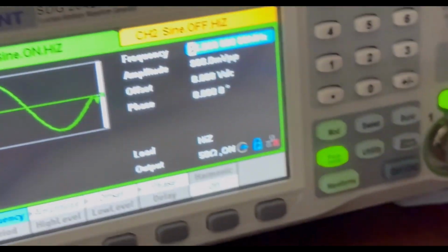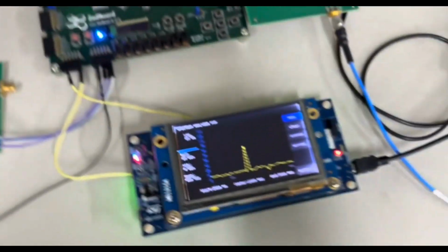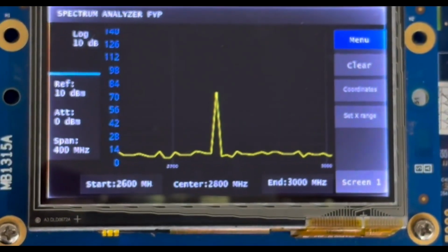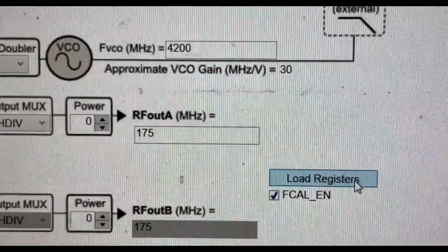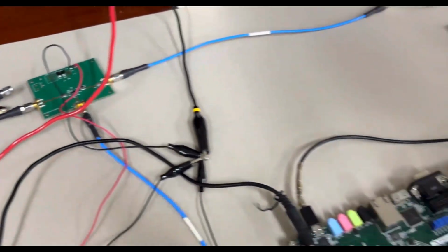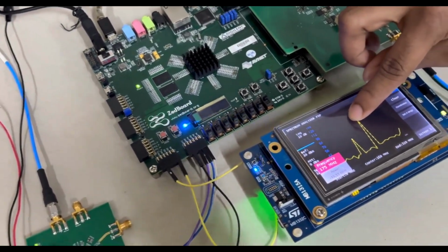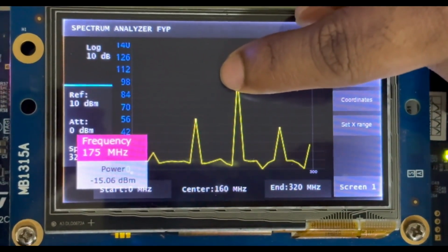We have successfully built a modular scalable spectrum analyzer that delivers accurate results at a lower price point. The minimum resolution bandwidth is 5 MHz and can be extended to 1 MHz with the same hardware setup, as the limitation here lies in the filter bandwidth and the display rendering capabilities. The sweeping time is around 180 milliseconds for 300 points, and the maximum RF signal power it can handle is 10 dBm. Due to losses in the standalone PCB connectors, wires, and the use of non-low-loss PCB materials, the minimum detectable power is negative 30 dBm. However, with an upgrade, we can detect much lower signal power.